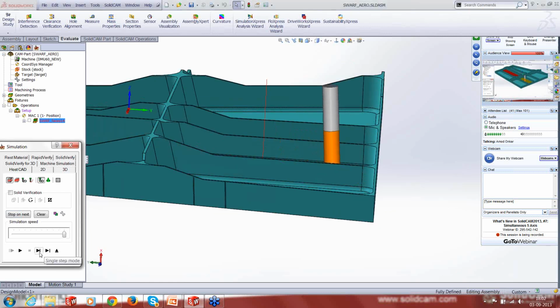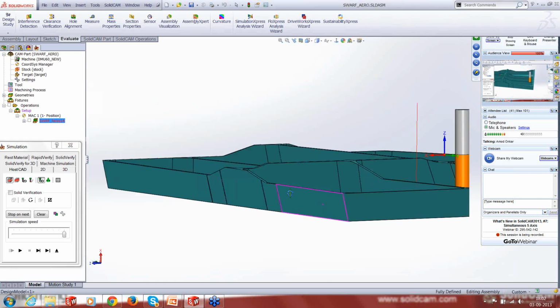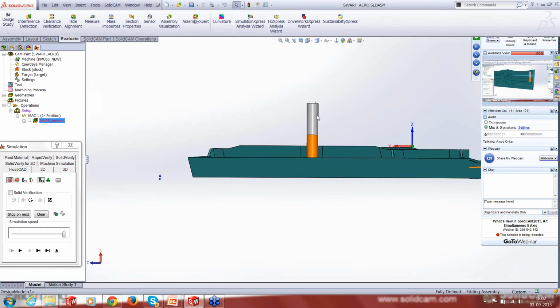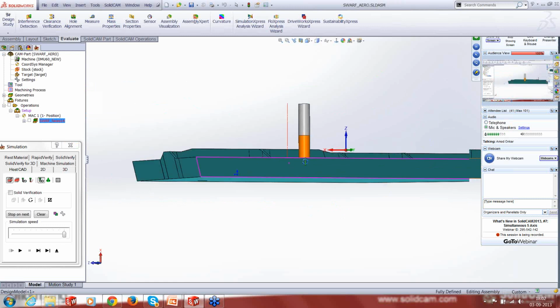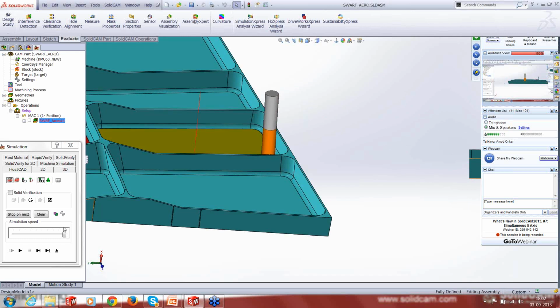So now it's going on to become almost straight because the wall that it is approaching is straight. But when you look at this view, it is still having a draft. It's doing the undercut milling, but it already knows that it is approaching another wall, so it's tilting itself to that other wall, but it is keeping the tilt of the other surface constant while it is changing the lag angle.